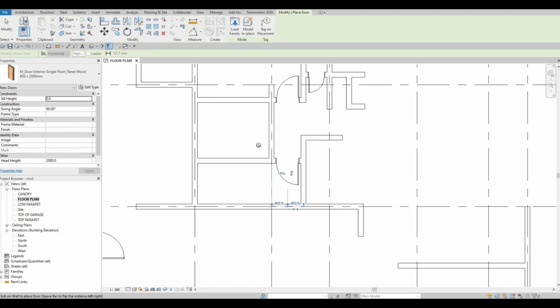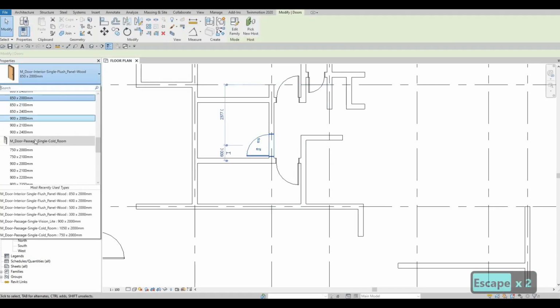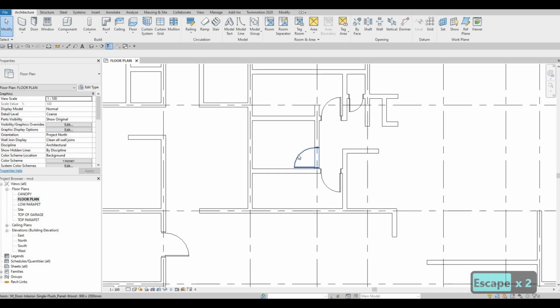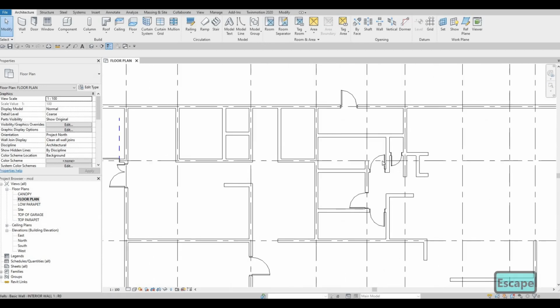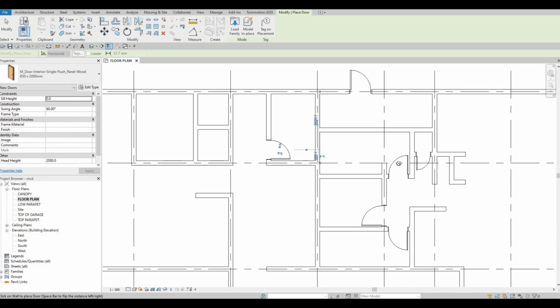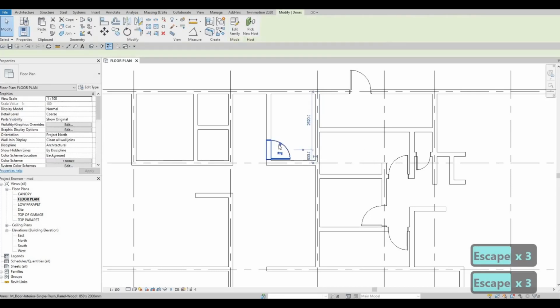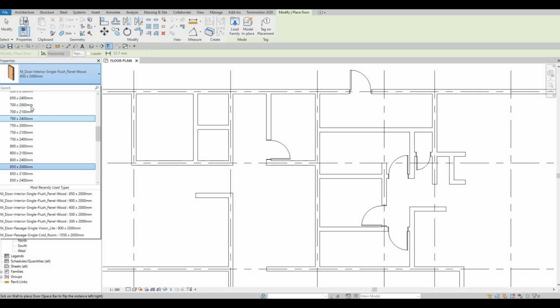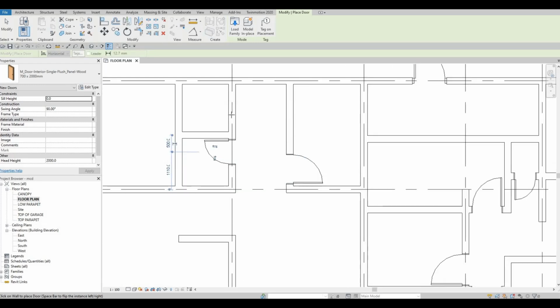And then for the universal washroom, let's make it bigger because they will need it. Let's put it at 900. So that makes a big difference, especially for wheelchair. And then now CS again. I'm using the 850, and let's add the one for the managers. And then for the crew washroom, let's make it smaller. So here I'm gonna do CS, but we're gonna change this to, I think, 600 or 700 will be good enough. Yeah, 700 for the washroom.